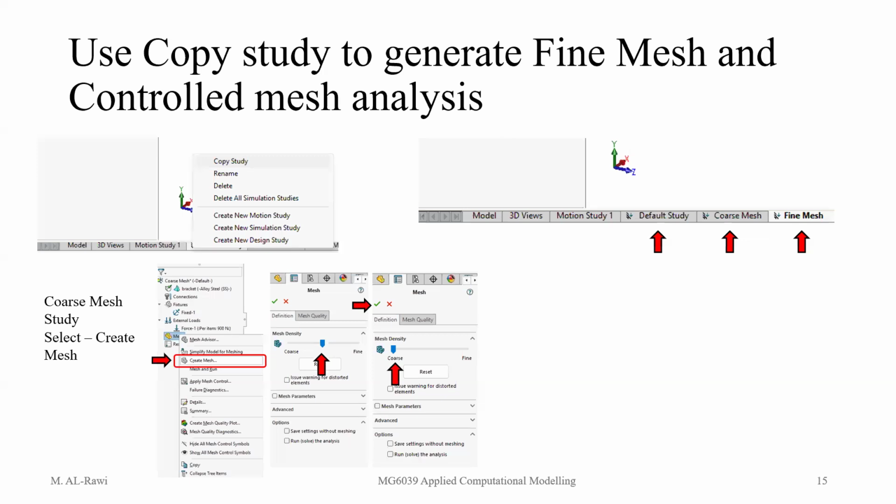Okay? Still there, don't do anything. Follow me step by step. Now you get the mesh. As soon as you do it, the software will create the coarse mesh, which has really very big elements. Mine created small mesh on fillets. That's fine, that's not bad. Still, we haven't done the control on it. Possibly you have the new edition.